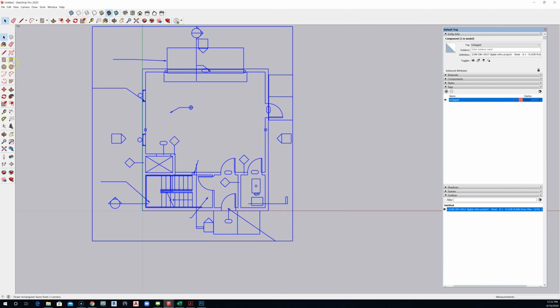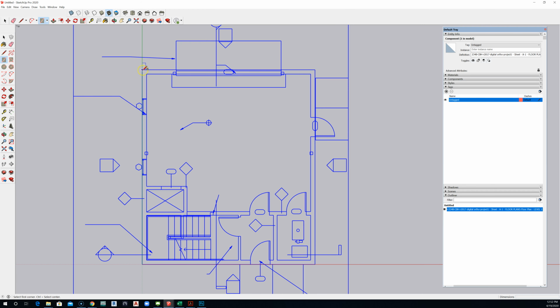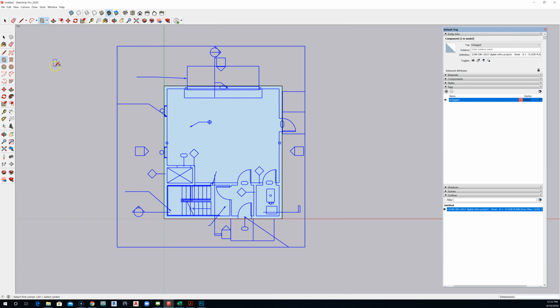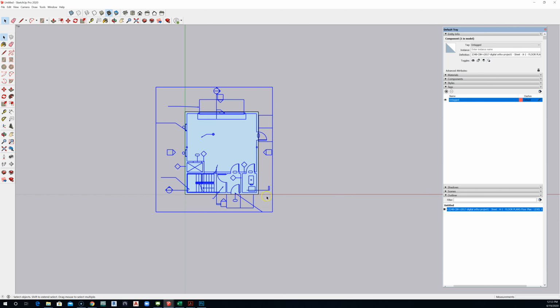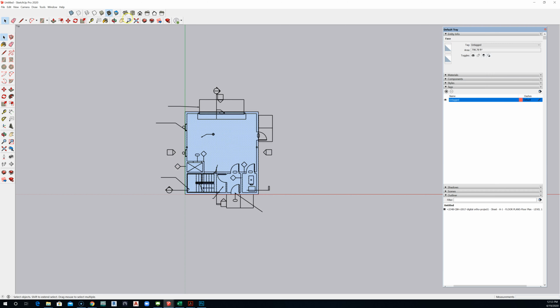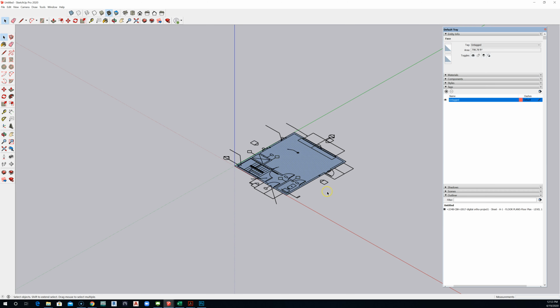So now I want to model a floor slab. Remember, we decided the length and the width, 26.4 by 34, and we extruded downwards 16 inches. Let's go to an isometric view, push-pull, down, 16, see the control box, enter.